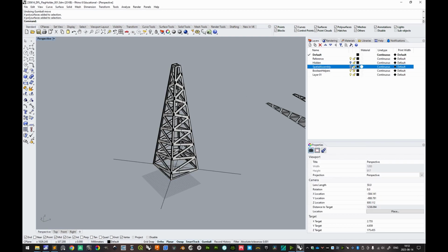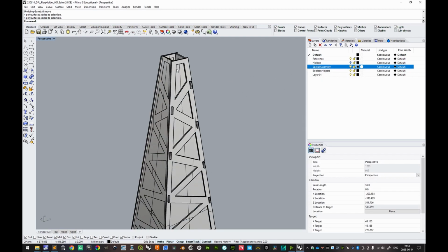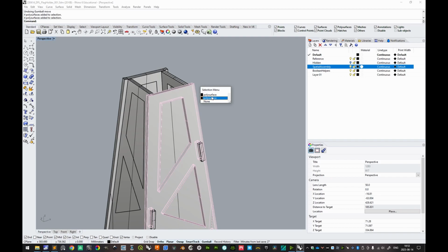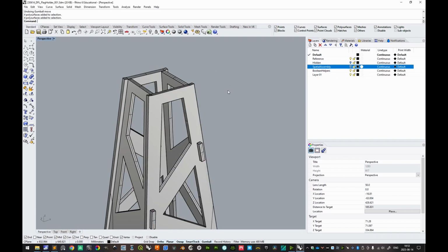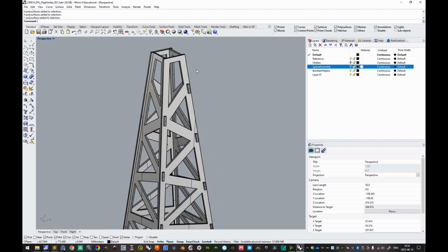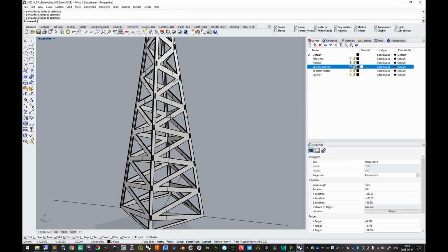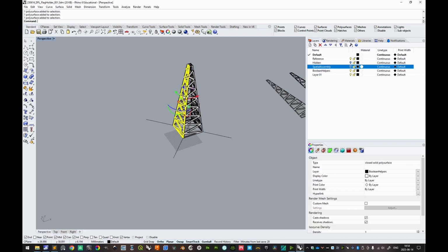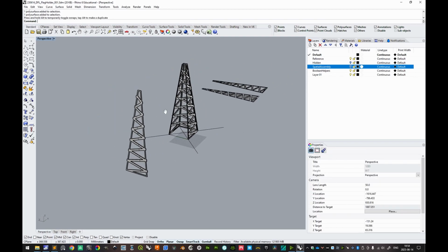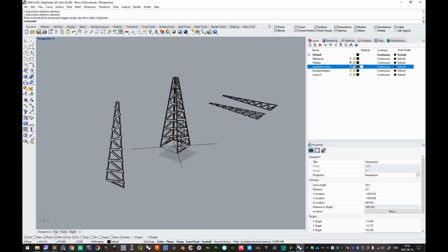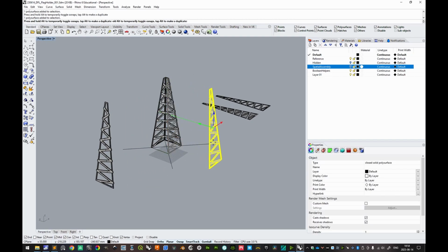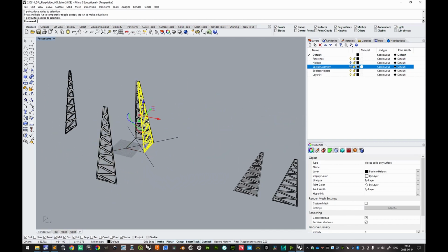Very good. Now there should be duplicates. Exactly, you see that there are 2. But now that we hide it, there's only 1, so that means we have a duplicate copy in the spatial assembly layer. Very good. Then, it's not essential, but it's good for consistency to make sure that you have a front and a back. The outside here will be treated as the front and the inside as the back. So we'll simply move these like this.